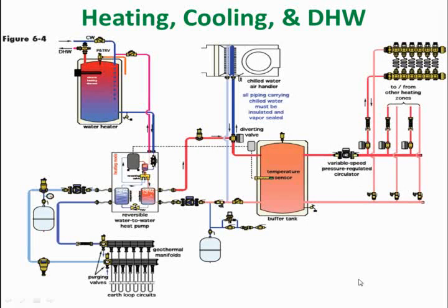All right, now here's a system that's going to do heating and cooling. Up until now, we've been talking pretty much about heating applications, but let's say you've got a job. Maybe this is in an area like in Colorado or something where they've got a month or two in the summer where they need a little bit of cooling application. So what we've done in this one here, now we've got the heat pump, same desuperheater here to make a little bit of domestic hot water in the tank up here, backup element as we talked about.